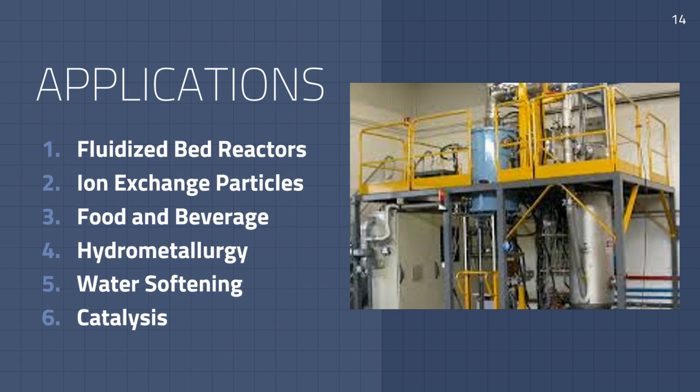The application of fluidization is in fluidized bed reactors, ion exchange particles, food and beverage, hydrometallurgy, water softening, and catalysis. Its common application in the industry is to mix all components in a fixed ratio. However, the type of fluid to be used depends on the application. In common cases, the usage of a gas as a fluid is observed in combustion mechanism or for mixing process, as gases do not react with particles or particles are not soluble in gases. So, mixing particles with other particles can easily be done by fluidizing it with a gas.